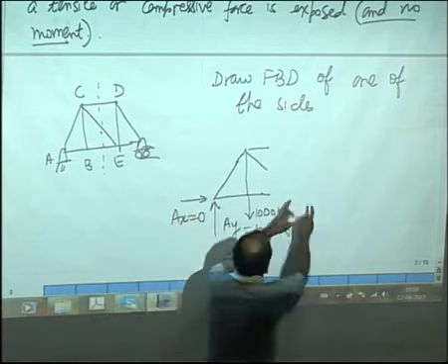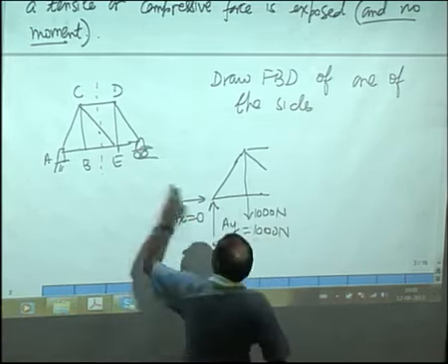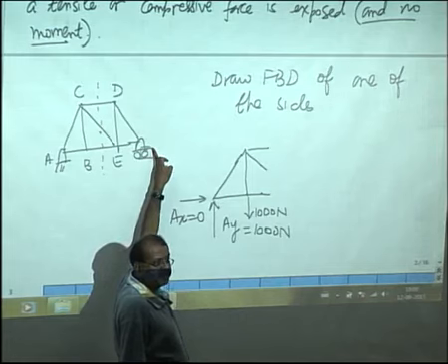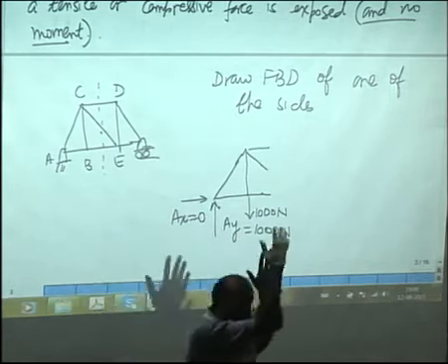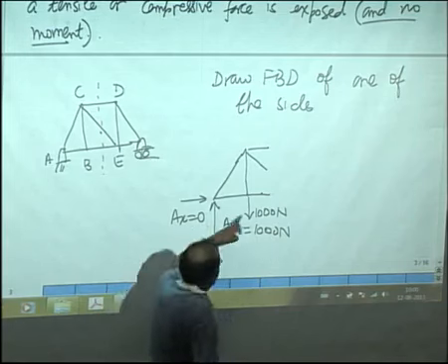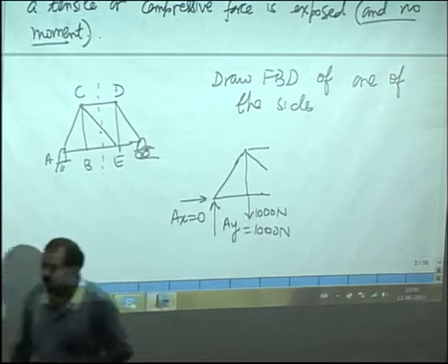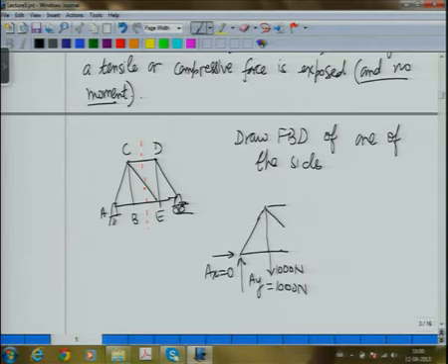I will not show the forces on point E and point F, because they are not a part of this truss. I have made a cut, so I only show the external forces acting here. In addition to these external forces, so now this was basically point A, this is point B, this is point C. Now there are these three unknowns, there are three cuts. So here I will show CD, CE and BE.